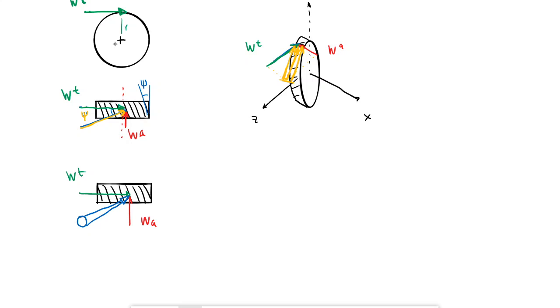And the angle, sorry, that is made between this blue vector in 3D coming out of the screen into the screen and the yellow plane here would be phi, the pressure angle, right? So if I do a 3D version of those vectors, I'll get something like this.